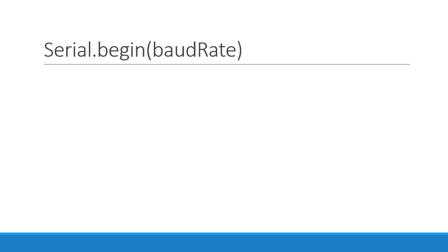So if you do not set the Serial.begin function in the void setup, it will not initialize your serial monitor, and hence you will not see anything on your serial monitor. Don't worry, you are going to see how the serial monitor looks in the next recording video. But here I just want to discuss the functions that we'll be using.